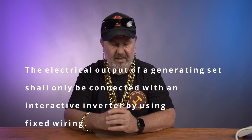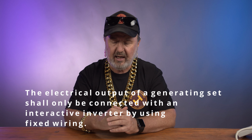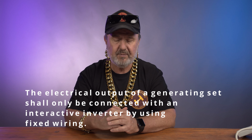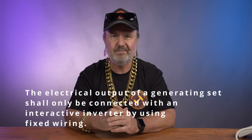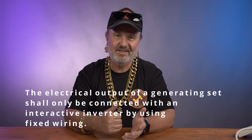So that's one of the reasons why in AS/NZS 4509 Part 1, we specify that the electrical output of a generating set shall only be connected with an interactive inverter using permanent fixed wiring to a dedicated circuit breaker. So it's not a plug, it's not a socket inlet with an extension cord plugged into a generator.